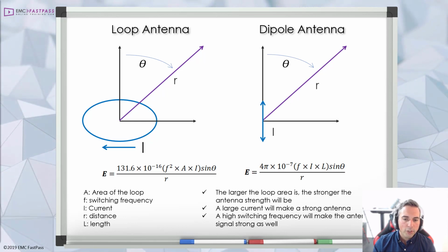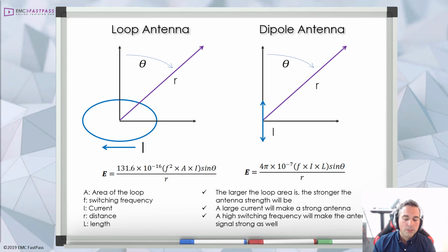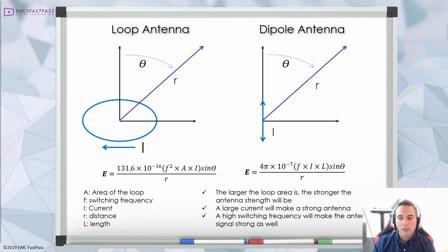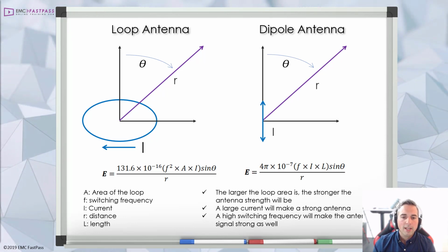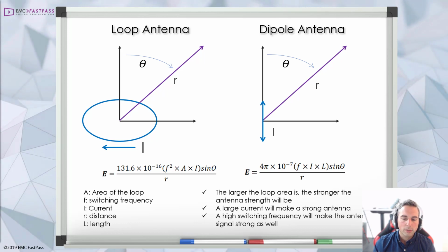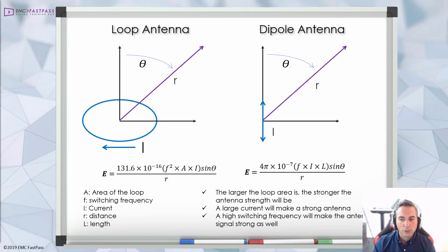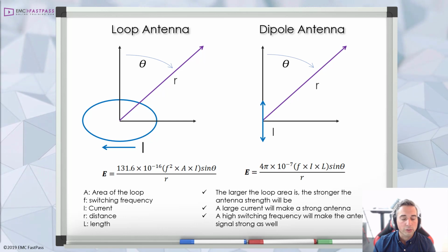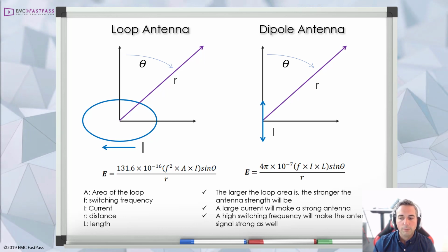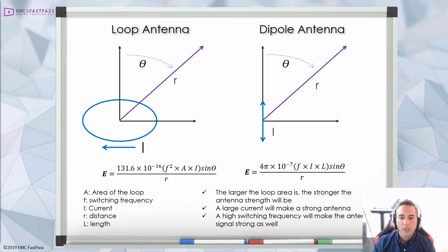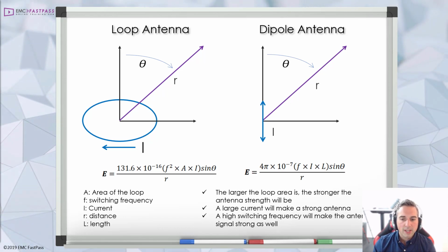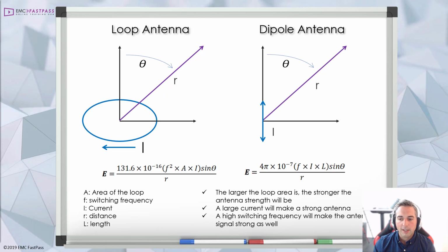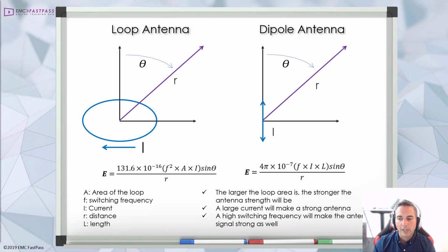And as an example, an excitation frequency of, say, 100 megahertz with a common mode current in the order of microamps, that's likely to cause more trouble in terms of emissions than a differential mode current in the order of milliamps at the same frequency of 100 megahertz. So that's what these equations point to. Now, above a gigahertz, the f squared term becomes dominant and differential mode currents tend to be our enemy.